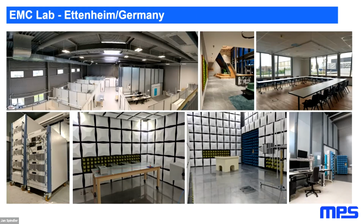On this, as you see here, you have no wooden table with a metallic ground plane. You have a plastic table where you can place a DUT, which is a tabletop. And if you don't have a tabletop, like a washing machine or something like this, you place it directly on the floor. Additionally, you have a much higher height to move the antenna to find the points, and you have a turntable inside as well.